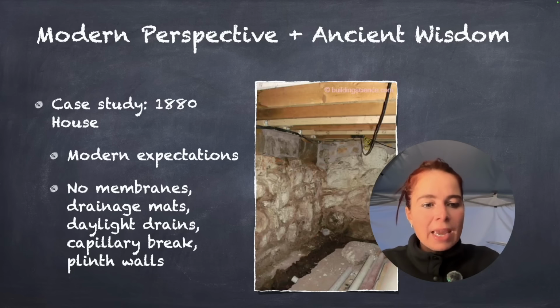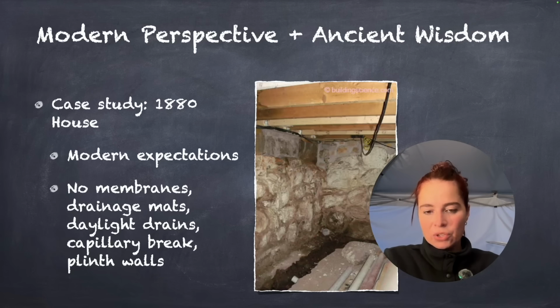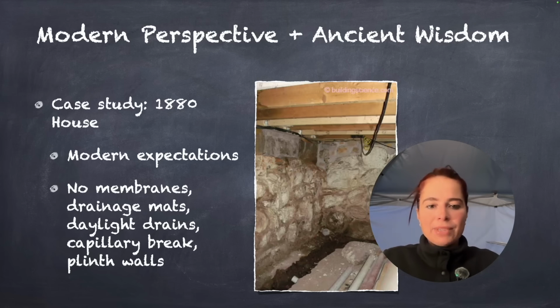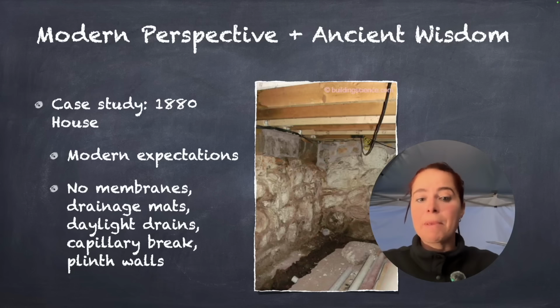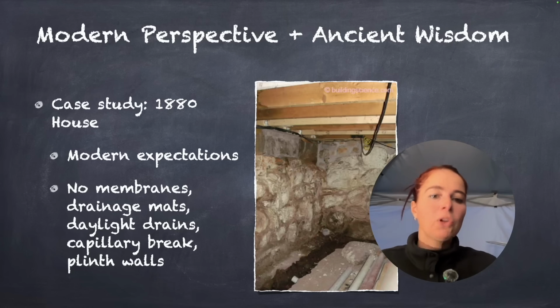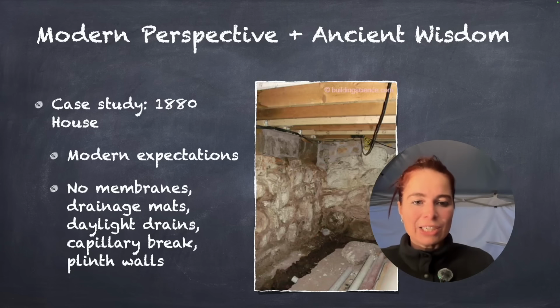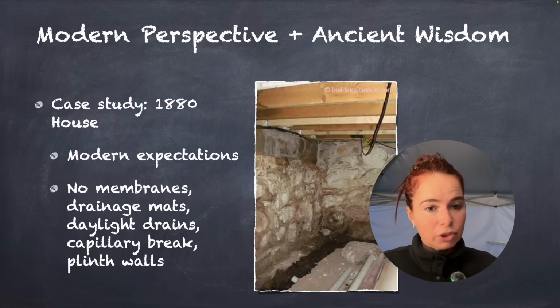It was below grade, it created a crawl space, and it was right up against the moist soil with no attempt to stop water coming in, because back then they didn't even really understand capillarity. This idea of creating a crawl space below grade was really quite a new one that would then be part of the building envelope. You had the full hydrostatic pressure, that water pressure in the soil pressing onto those walls. So of course they would have gotten saturated with all that mortar between the stones. So yeah, this is not what I'm talking about when I talk about a rubble trench foundation. Don't do that.